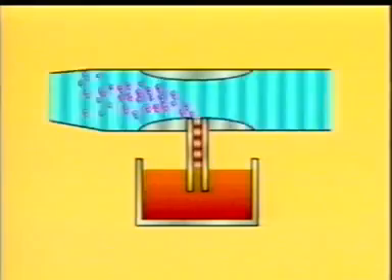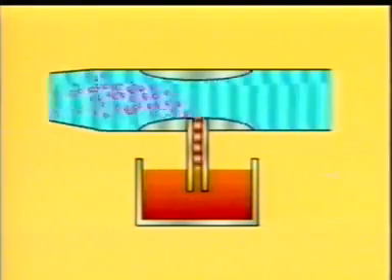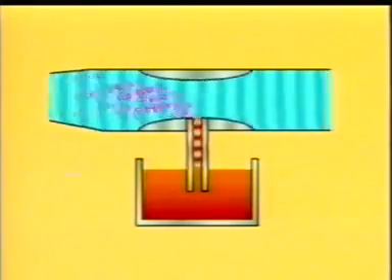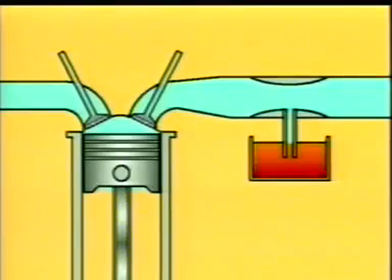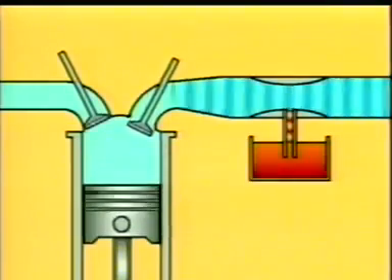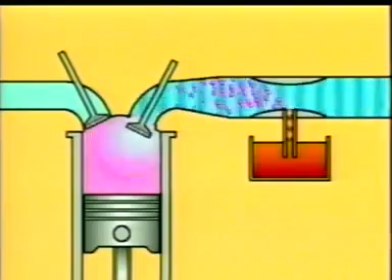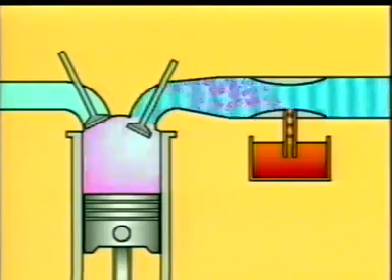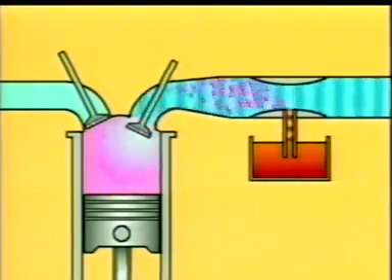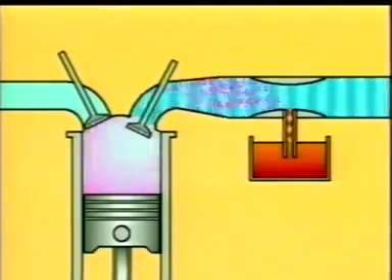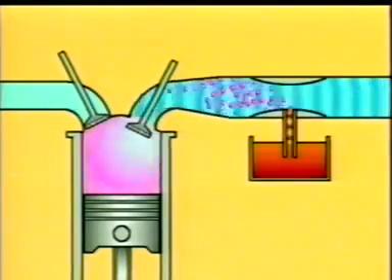The carburetor uses this Venturi to draw in fuel and turn it into a spray. When the piston moves downward during the engine intake process, air comes flowing into the cylinder. At this point, negative pressure is created at the Venturi so that fuel is drawn into the carburetor, turned into a spray and mixed with the air.